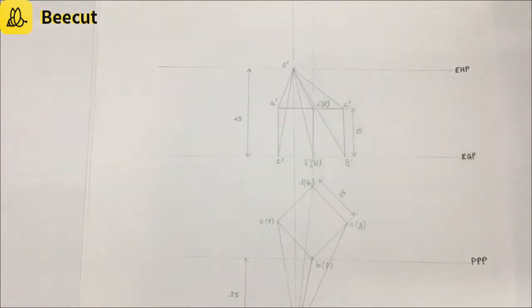After completing the top view as well as the front view, the next step is to locate the central plane. The central plane is a plane on which the observer is looking. In the question, it will be stated either that it is lying towards the left or towards the right. Just as in the previous problems, here also it is stated that it is towards the left of the center of the cube.